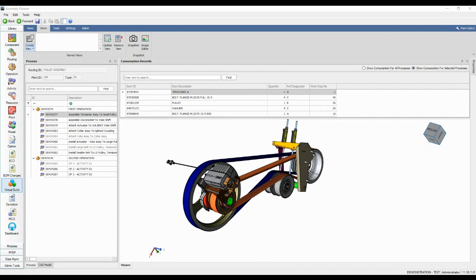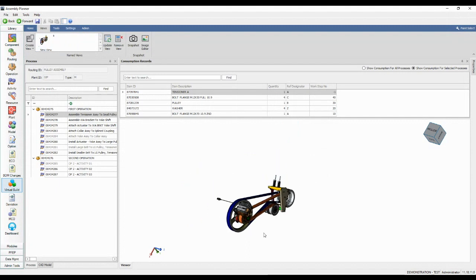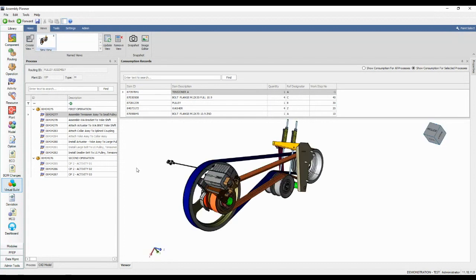You can drop the Create View button down. You supply a name. Again, this has to be unique, I think, for obvious reasons to keep things segregated and identified. For your reference, it's optional, you can also define a description. When we click Save, then we can see that a view has been created. So to demonstrate this, if my model were like this, for instance, and I want to get back to that view, I can click that and snap back to right where I was.